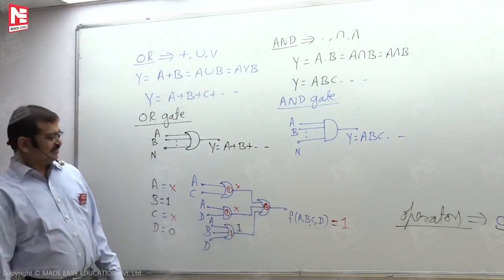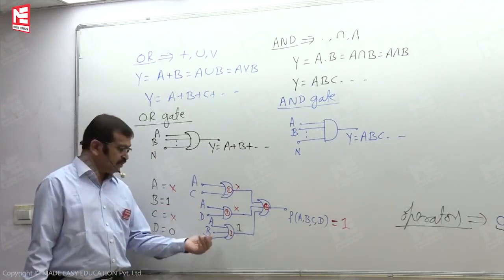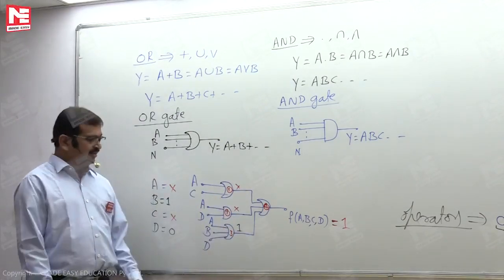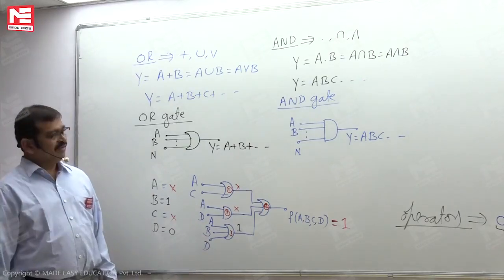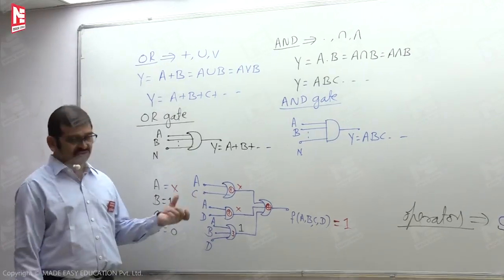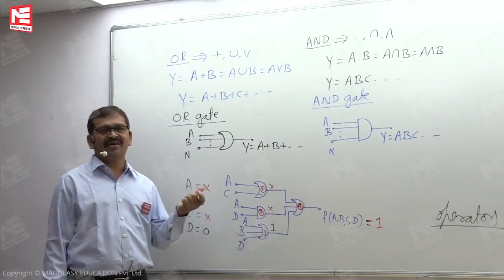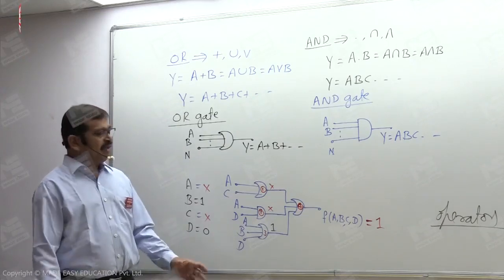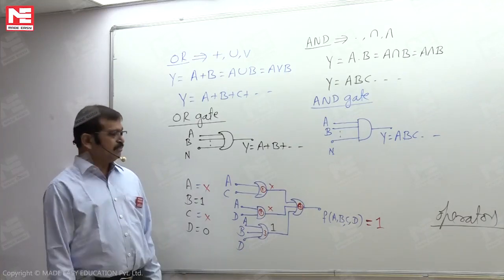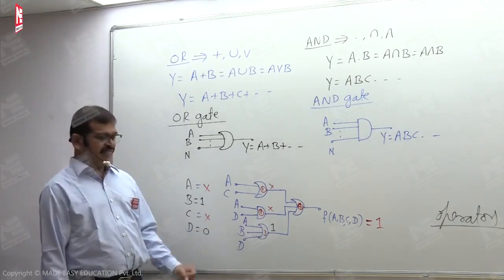So, without wasting time to find the gate 1 output and gate 2 output, just by looking at gate 3, where one of the inputs B is 1, we can state the answer without much work. The circuit output is 1. Of course, I quoted a very simple example based on the gates we discussed till now. But this type of circuit may use other gates like NAND, NOR, XOR or XNOR gates, it may be anything. With truth table knowledge of the respective logic gates, sometimes it is possible to state the result of the circuit with less paperwork.